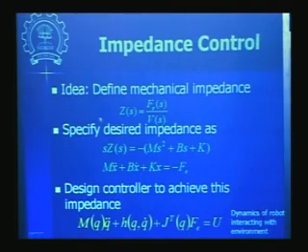Now let us see just some gist about impedance control. The basic idea of impedance control is to define a mechanical impedance in this fashion. It is a ratio of force versus velocity, and then we specify the desired impedance in this fashion. So this impedance concept is basically similar to impedance in the electrical domain.